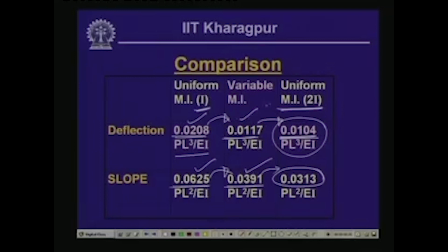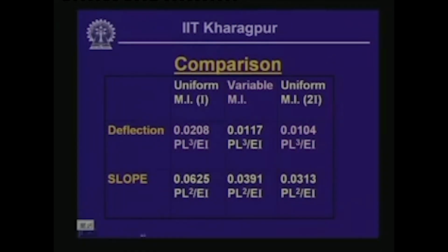So, by making variable moment of inertia, in fact we can achieve economy both in terms of the deflection or the stresses, as well as the economization on the usage of the material, and thereby where we have the larger value of the bending moment, if we go for a larger cross sectional area, thereby you can have less stress, you can have less deflection, you can have less value of the rotations at the end.